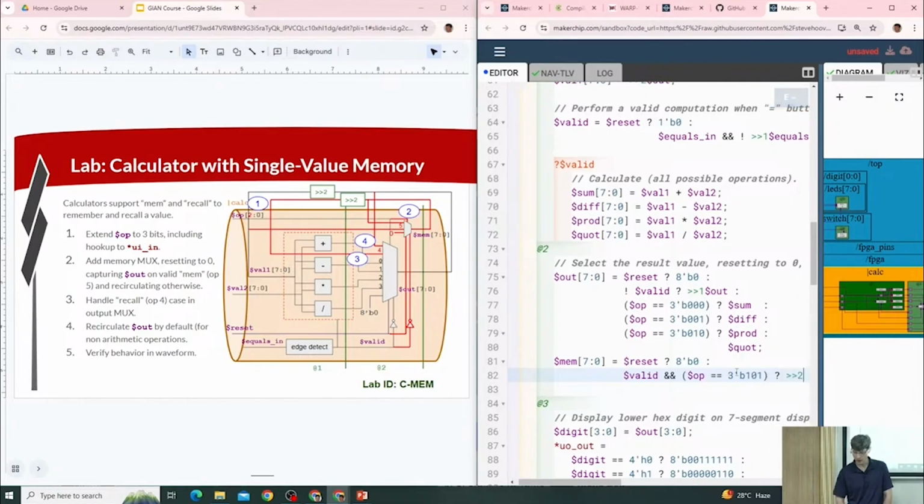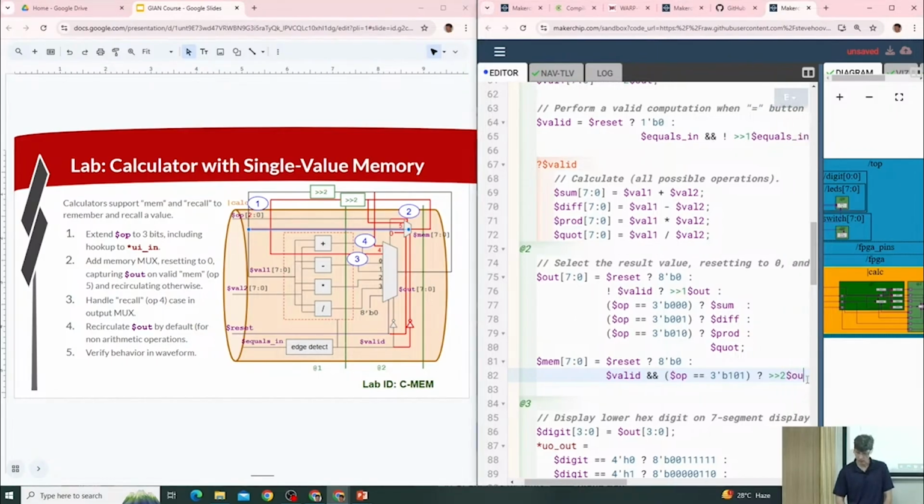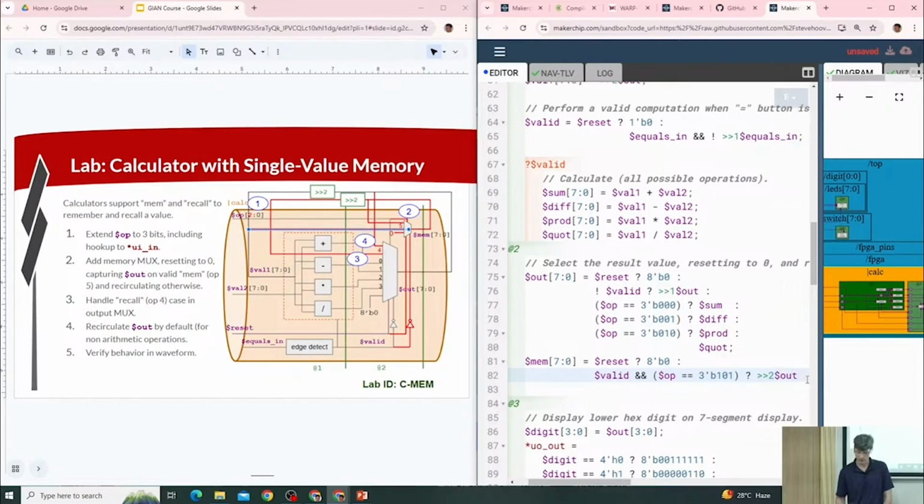Then the value that we want, okay, so we are here. Taking the value from the output mux, but with a 2-cycle delay. So I'm taking the value from the output mux from the operation that happened 2 cycles earlier in the pipeline. So that means a reference of ahead by 2. And this is from out.